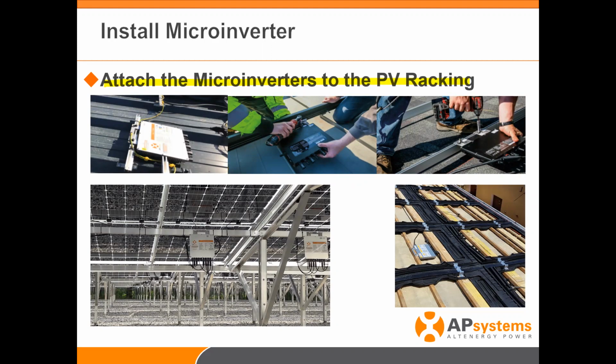Number one is, especially in the northern climates, we want to make sure that when there's a heavy snow load on the devices, the module itself is not coming in contact with the inverter, because of the deflection of the module. Second is we want to make sure there's good proper cooling as well. It's a warm environment sitting on these roofs, so we want to make sure that there's good airflow around the device, so we have that convective cooling going around.